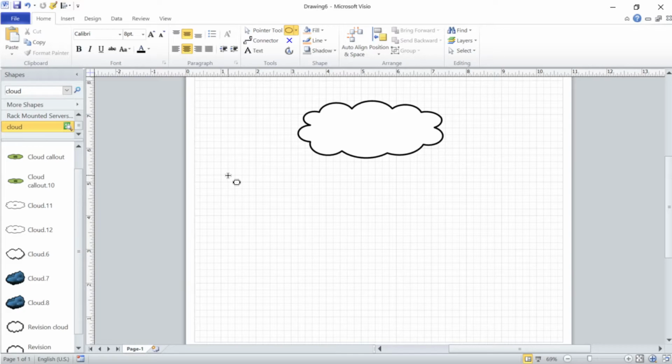Click the left mouse key, drag to where you can almost see there's two cursors that lay over top of each other. The one in the back is the one that is snapping to the geometry of the grid. Get that cursor that's floating in the back to sit right on the corners of the squares, and you'll have yourself a perfect circle. Let up on the mouse key.